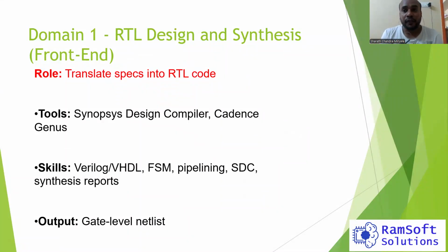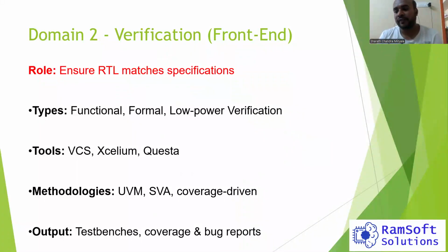If you are from the RTL design team, you will generate a gate level netlist, and you will pass this gate level netlist to the other team. So what you're going to do in this step is literally turn your idea into digital logic. Number two, verification.